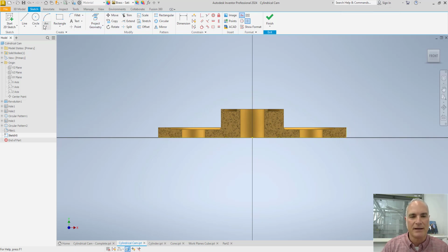And the reason I'm doing that is because when I create my angle here, I want this to go from that corner, and I'm going to do it about 7.5 degrees here. Now, it's always a good idea to constrain your sketches, so I'm going to give this a constraint between this point and that point there, and then I need a dimension between these two, and again, I'll make this about 7.5 degrees. This sketch is fully constrained.